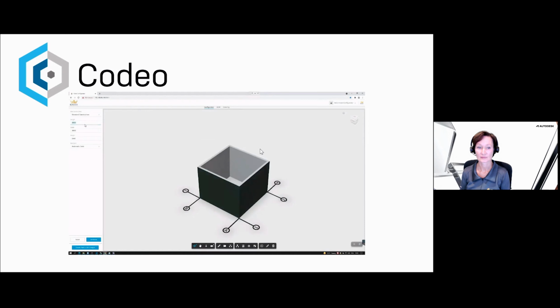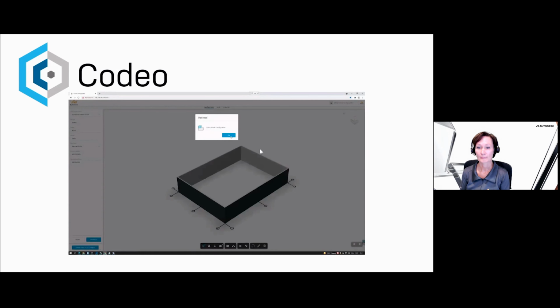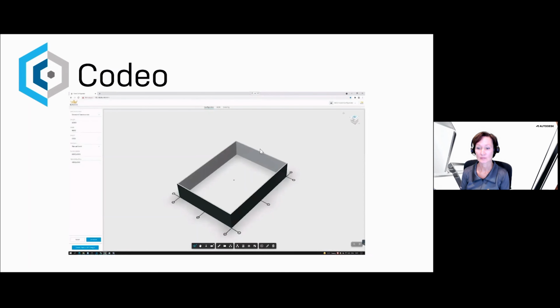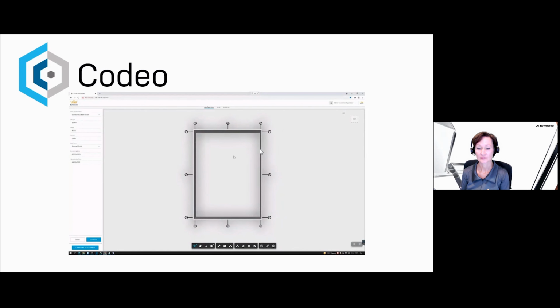Let's see the top view, and I'm gonna change the length parameter, gonna change the width parameter and height parameter. I'm gonna select manual joint and enter each wall length just like that, and generate the kiosk. Updated. So let's view the top and let's see the grid plan.